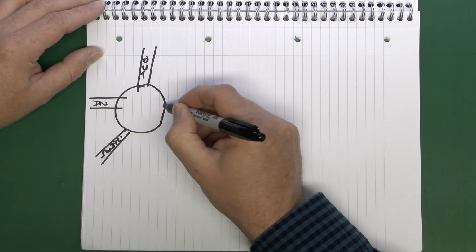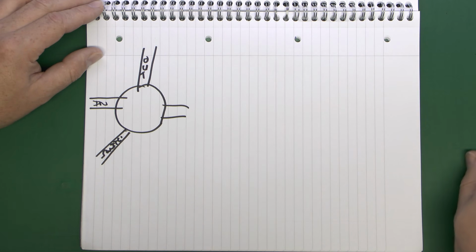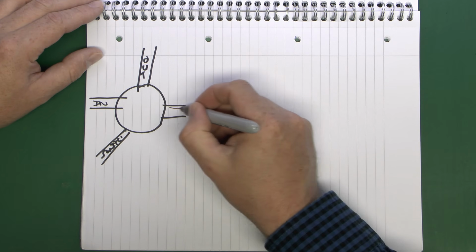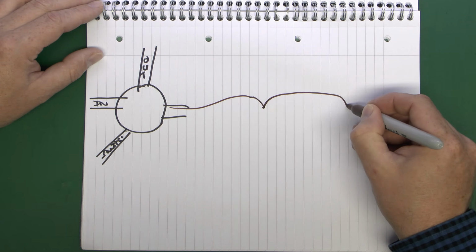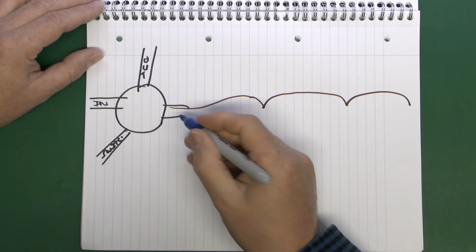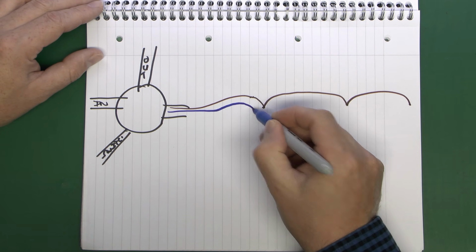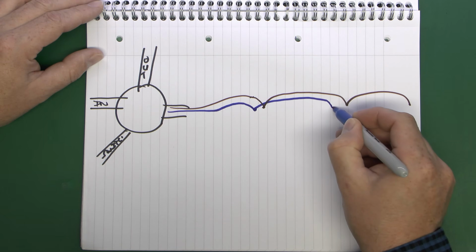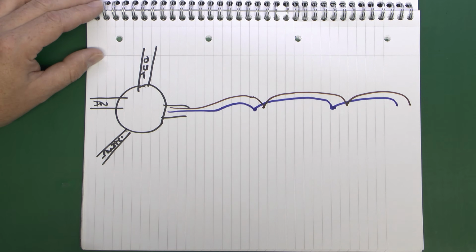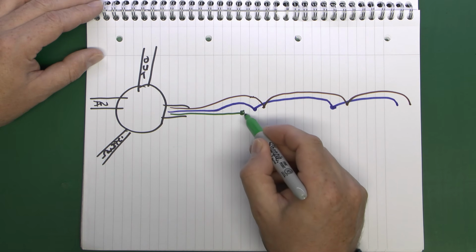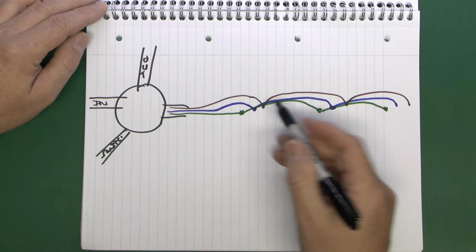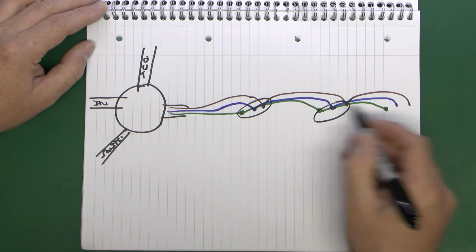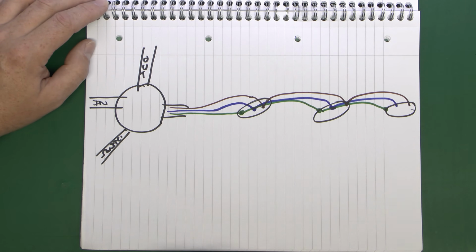And then the wires that come out for the actual ceiling rose where the lamp would be fitted, you're going to have your line, neutral and earth, and you can go to your first light and then simply connect into the second one and into the third one. And then of course the same with the neutral as well. And again with the earth also. And that would be commonly used, say, with multiple lights in the room, so you'd have one downlighter here, another one here, and a third one there, and in fact as many as you actually wanted. So then they'll all just turn on at the same time.